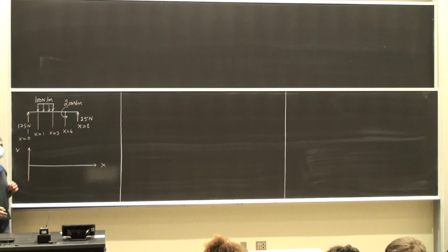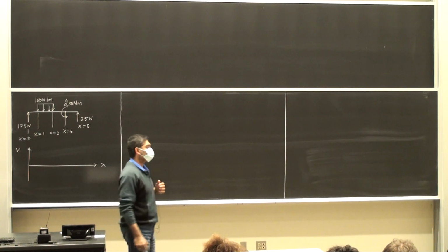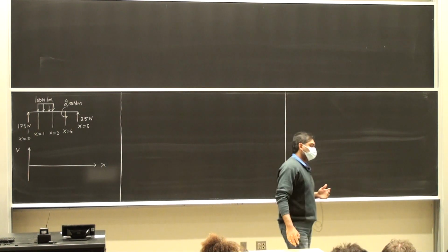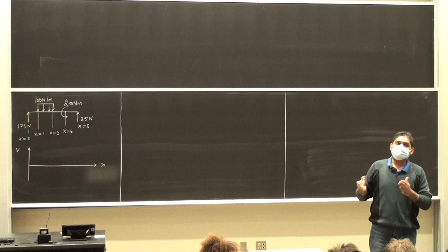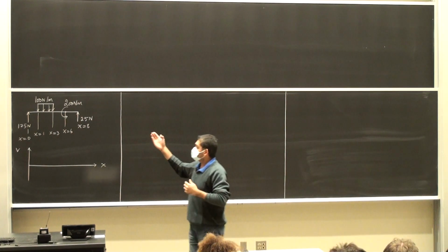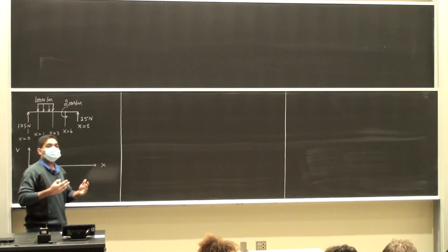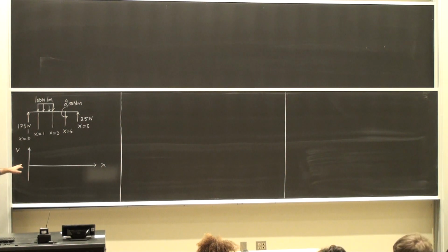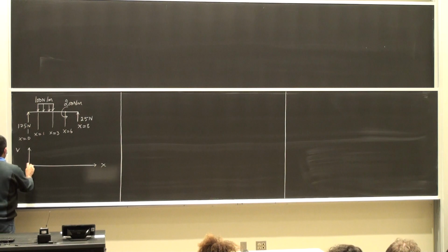So what I want to do in the next problem is, at least with the shear force diagram, when we draw the shear force diagram, I don't want to perform calculations. I want to see the load distribution that is acting on the beam and then directly start drawing it out. So here is how I look at it. This is how I do these things. 175 newtons, concentrated force pointing up. Start there from 0.